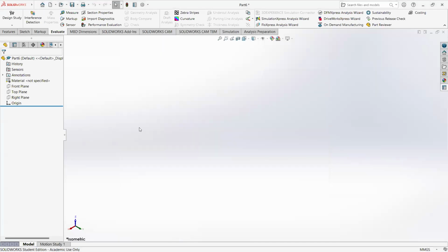The second thing I noticed is that all the parts give a material. They do that because rather than check to see if the part was modeled exactly the way that they did it, what they're ultimately going to ask on most of the questions is to give the mass of the part that you end up with. And there's a tolerance, and I forget exactly what that tolerance is. You could be off by a little bit, but by giving a material, if the model is a reasonable facsimile of what they created, then your mass should match their mass, and you pass the test. They specify it right in the problem statement.